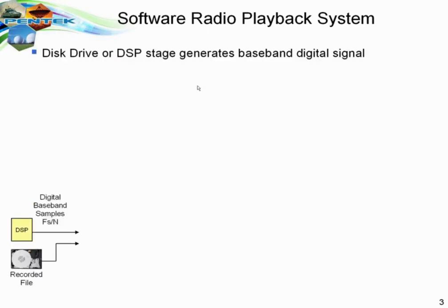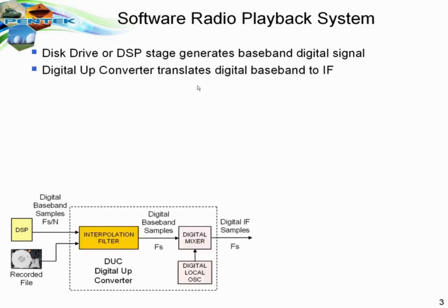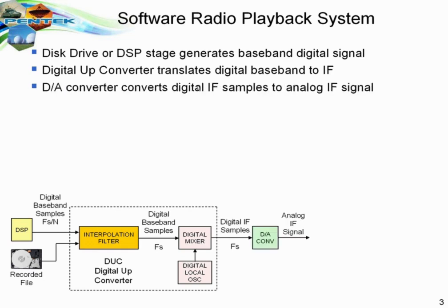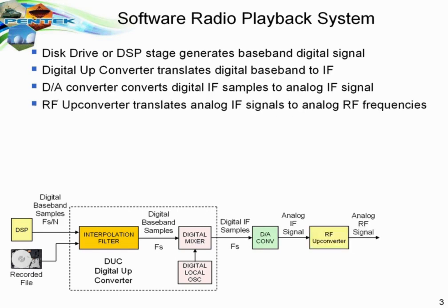At the front end, we use advanced, usually FPGA-based data acquisition modules like the one you see here, typically in a PCI Express board or VPX form factor with A to D converters and D to A converters. Currently, we're operating with A to D converters that run up to 3.6 gigahertz, D to A converters that are 1.25 gigahertz. These devices have to do the synchronization and the sampling, and they also include hardware DMA controllers that move the digitized data across the PCI Express interface to the rest of the system.